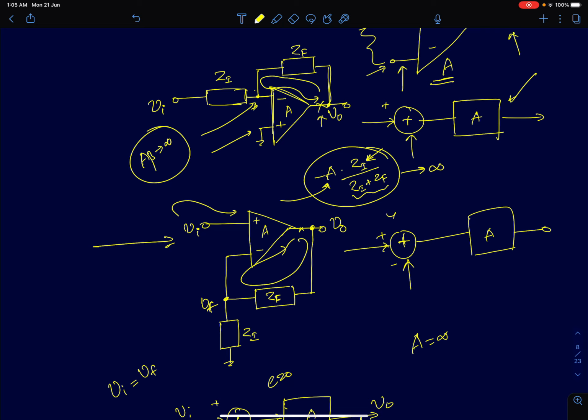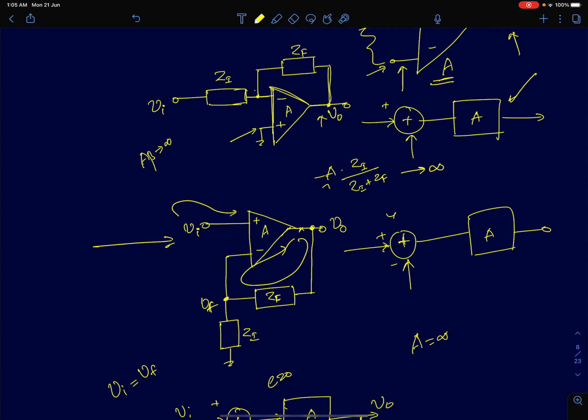If you use this, the analysis of operational amplifier circuits is quite trivial. First I'll quickly use that and show you what the voltage gain for the circuit will be, and then we will draw the conventional block diagram approach of solving an Opamp circuit. Since there is negative feedback, this node voltage is at 0, so this node voltage can also be assumed to be at 0.